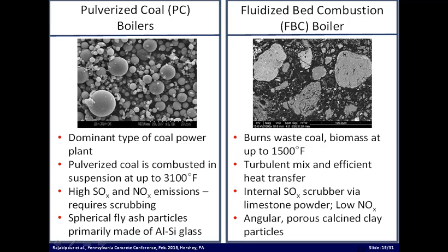But these temperatures are high enough that the mineral matter, essentially the clays that are intermixed with the coal, don't burn, they melt. And as they go up the smokestack in the flue gas, they solidify in the form of these glass spheres. And these glass spheres have several advantages for concrete, both chemically and physically.